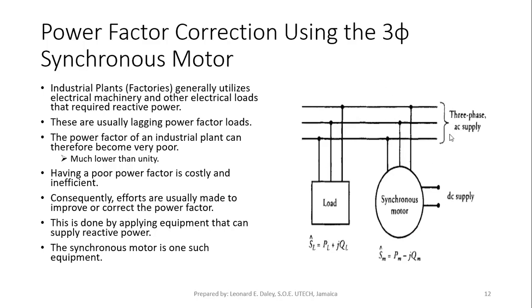All right, so you see a drawing here. The three-phase line is here, and this load here represents the factory. And then a synchronous motor here is connected to improve the power factor of the entire system. So the load plus synchronous motor becomes the system.